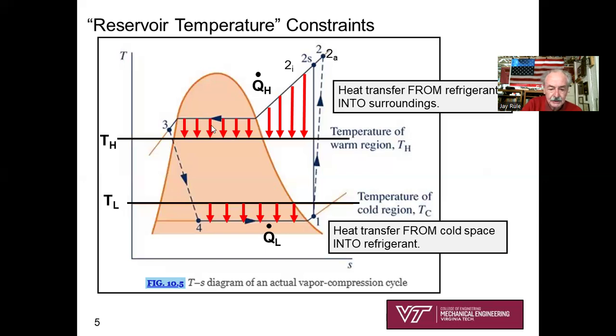As you get into the saturation zone, the irreversibility is less, but there is still irreversibility because we're transferring heat across a finite delta T. And so these red lines here give you a visibility of what that finite delta T is all about. So I wanted to depict that and share with you that we've got something irreversible going on between the refrigerant and the surroundings.